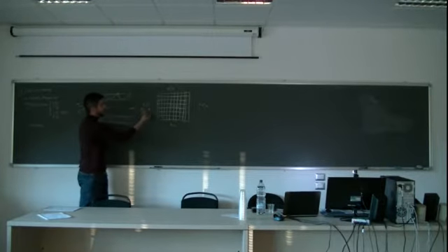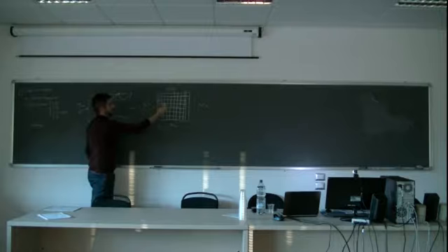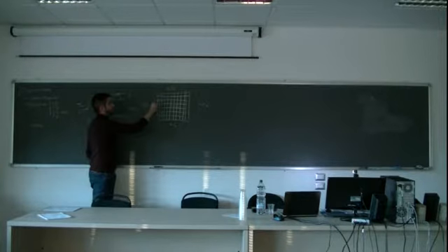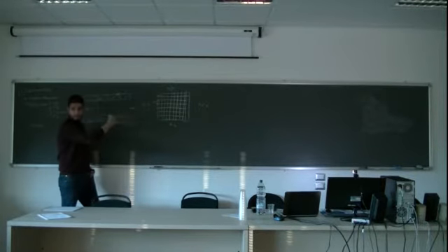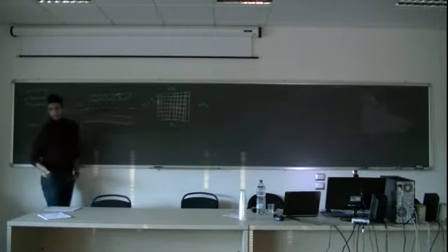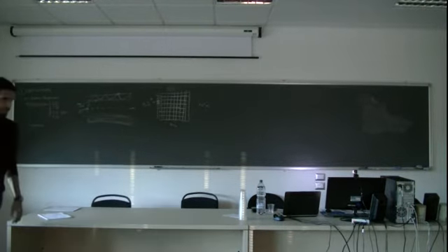This node evolves downward, because at the very beginning it was at 900, and it is touching something at 30 degrees, right? So it will start to dissipate heat outside. The temperature of this node will depend on this temperature, on this, on this, on this, and on the air temperature, right?